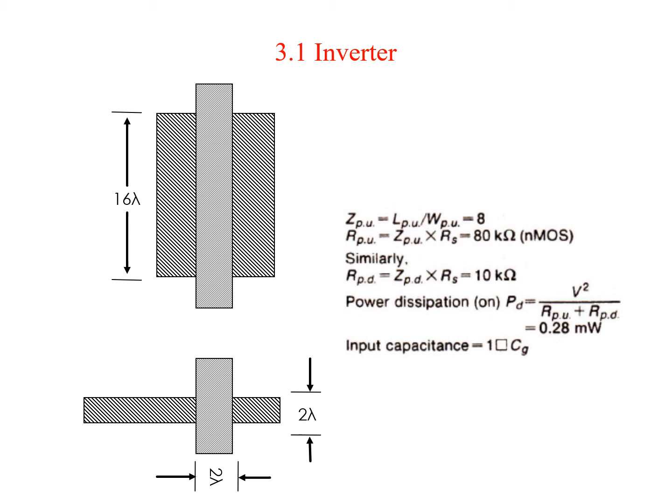Why does it have to be as small as possible? Because once you develop the entire architecture, whatever small heat is liberated by individual elements will get added on, and once the complete architecture is checked, the power dissipated by the entire architecture will be very large. So these small individual heat dissipations of your circuits should be as small as possible. This is for the first case.